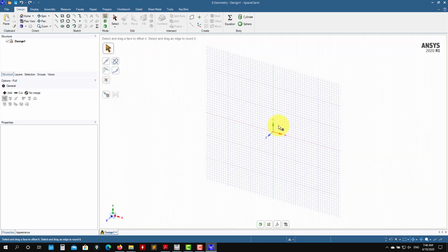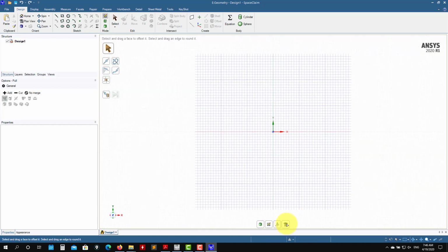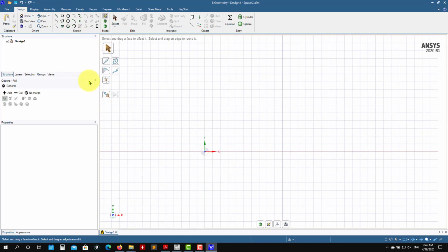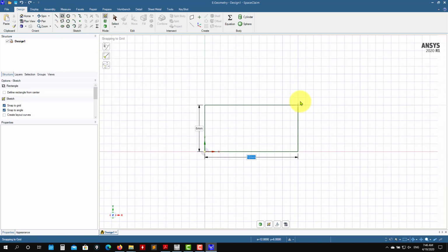I want to sketch using this plane, make it normal, and here you have all your options to do your 2D sketch. So like in the previous case, let's do it. You will see here that this one is much easier to use. Okay, so here we have it in millimeters. So let's do it there. Then we can do the scaling. Remember, when you pass to Fluent to do the scaling, I will leave it in millimeters.